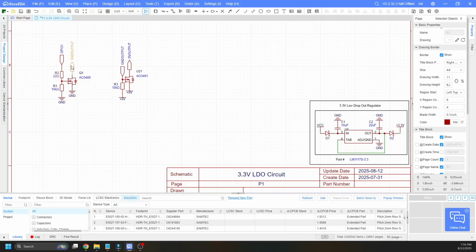That ground output is connected over here to this gate that also has a 10K pull-up that's on 5 volts. Well, it's isolated through the MOSFET, so we're not going to be getting 5 volts to come over here into this other side over here. It's isolated.